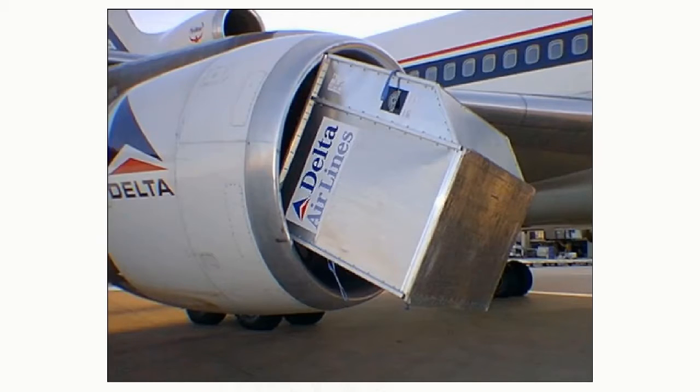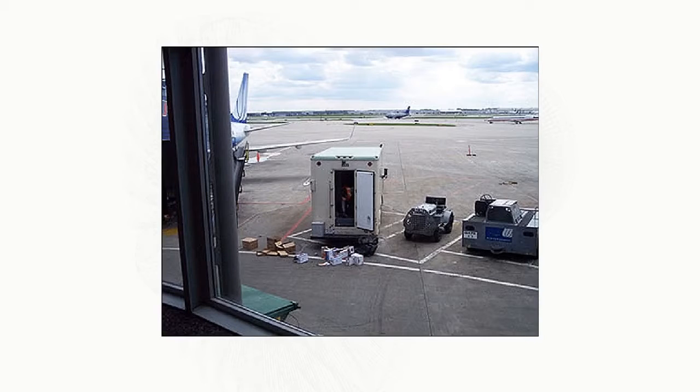This will most commonly occur while the aircraft is operating on or close to the ground. Damage to the compressor blades leads to changes in their geometry, which can cause performance deterioration, compressor stall, and even engine surge. As well as ensuring on the pre-flight check that the engine intakes are free of foreign objects, particular attention must also be paid to the area on the ground in front of the engine intakes prior to engine start, to ensure that it's free of loose stones and other debris.